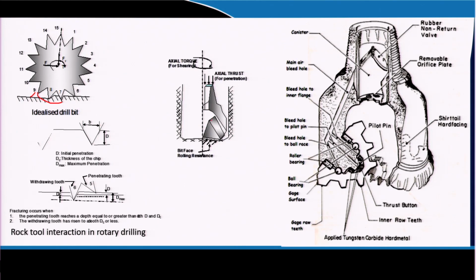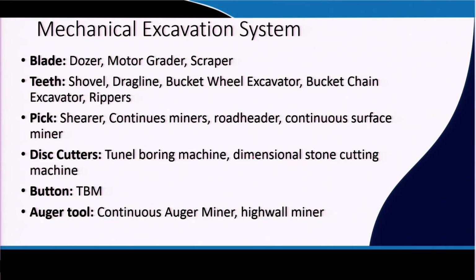Three cones are kept over there, that is why it is called a tricone roller, and the buttons or teeth are placed over here as a roll. The air is flowed through this. While cutting, a lot of heat is generated, so the drilling mud or drilling fluid goes through here and cools it, and the rock is cut this way. We will be discussing this in our drilling bits.